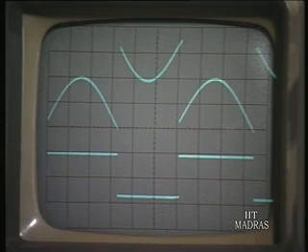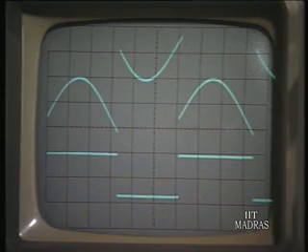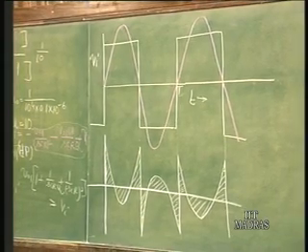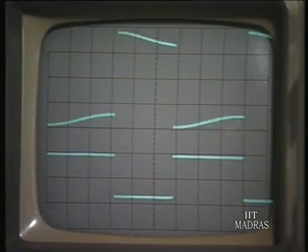This is the case only if the square wave frequency is the same as omega naught. If it is different, you will see that the output is going to be a square wave if the input is a square wave. Please change the frequency. Now the output is simply the square wave. On either side of omega naught, the output of the notch is a square wave, right.